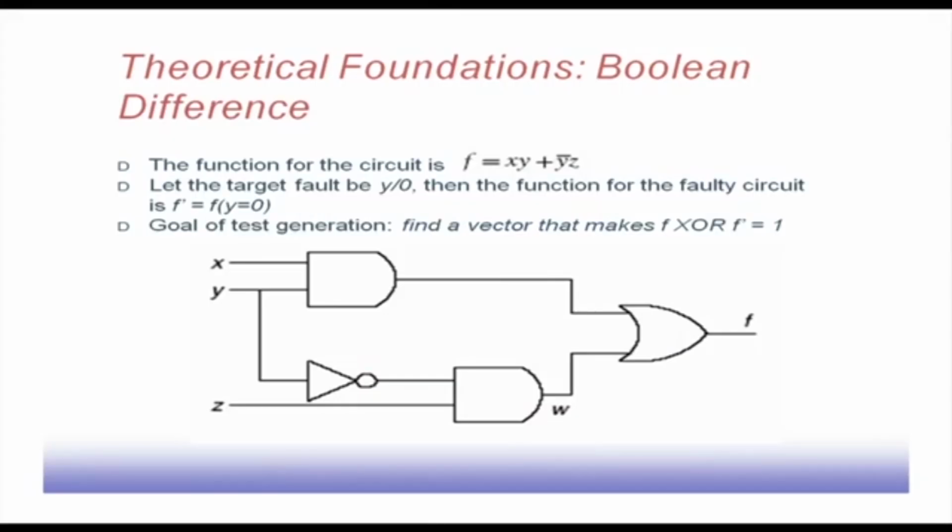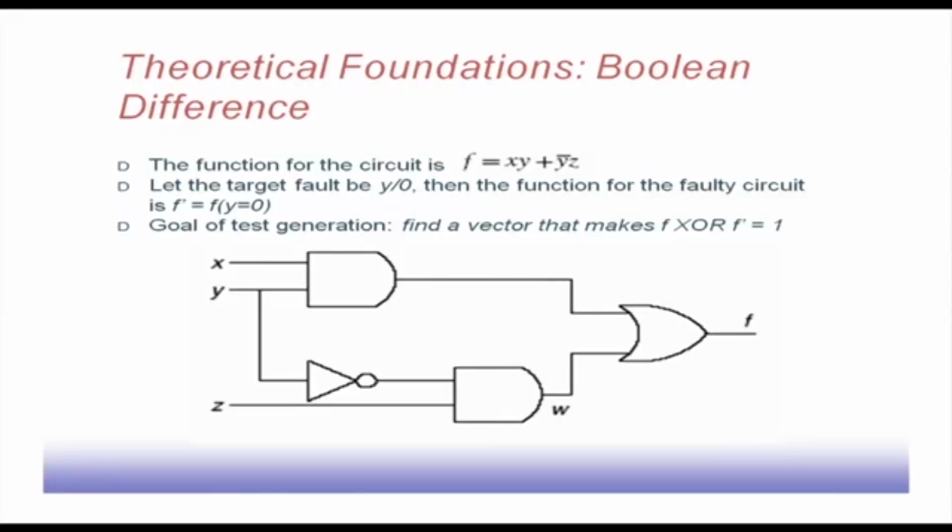So, next we will discuss this test pattern generation technique. But before going to the details of this test generation algorithm, we need to discuss some of the theoretical foundations of this testing process. They are based on one Boolean operation, which is known as the Boolean difference operation. This circuit is realizing the function f equal to x y plus y bar z.